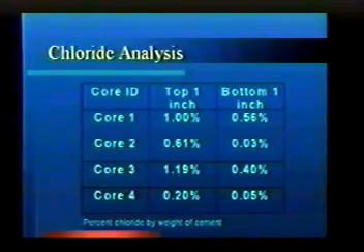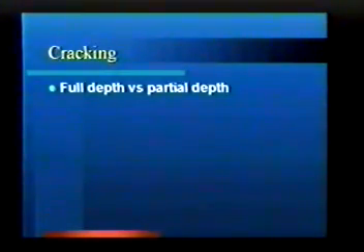Okay, in the chlorides, when we do a study, you always take cores and do chlorides top and bottom. Now you can also do it multiple times through the core, but if you can see, there's a variation. If there's a variation like this, we've got high chlorides from road salts, and maybe we've got chlorides from base concrete. So when you do a progression across the core, you can tell what you have.